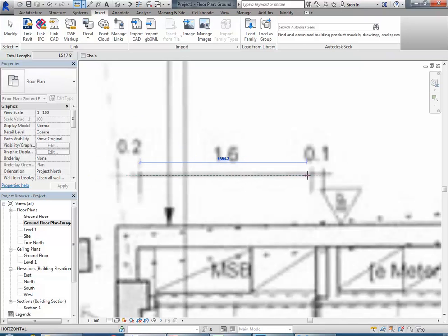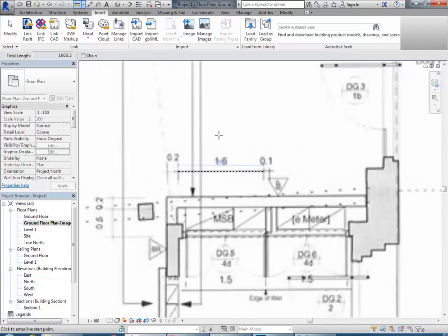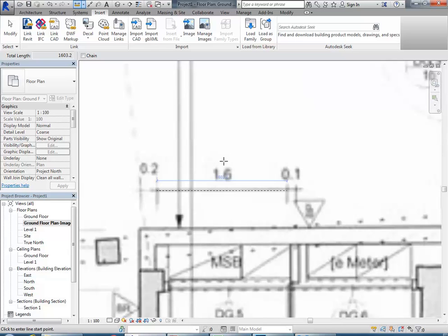Remember, with computers you measure to the centre of the line. I know with a lot of hand drawing people have this terrible habit of measuring to one side of the line, which is really old-fashioned and doesn't make sense. When you start scaling things, that just is totally illogical. So, centre of the line. And then to check it, measure it. So it should be 1600.